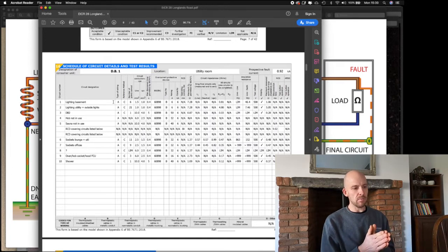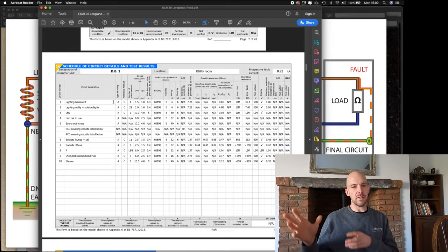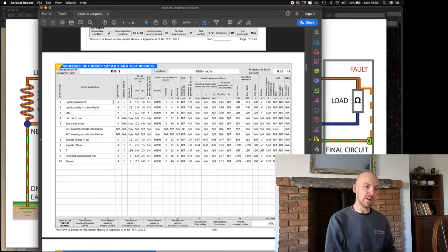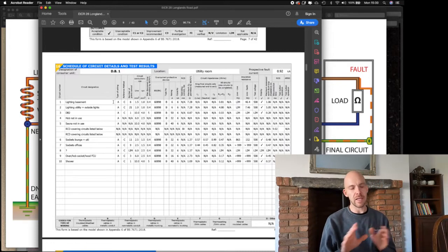Again, we note that down because there are lots of different types of cable, more often than not used in commercial industrial applications than domestic applications, but each of these different cable types, because of the way it's been made, will have different current carrying capacity. Some might be rated to be used outdoors, other cable isn't. And so yeah, there's lots of different factors involved, and for that reason the type of wiring is noted down.